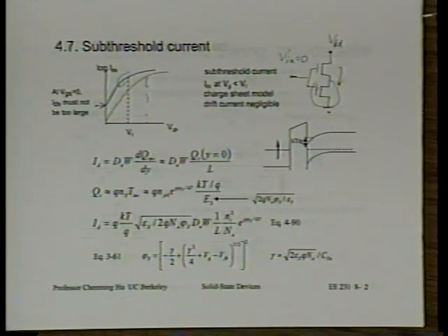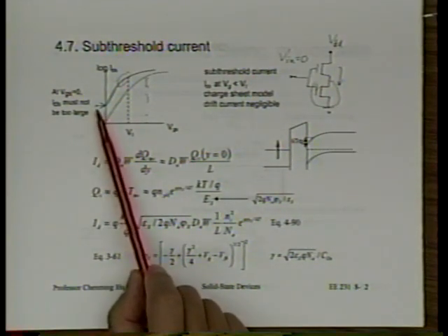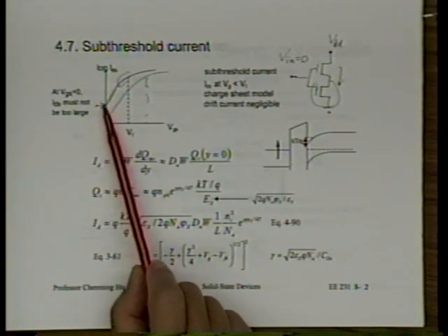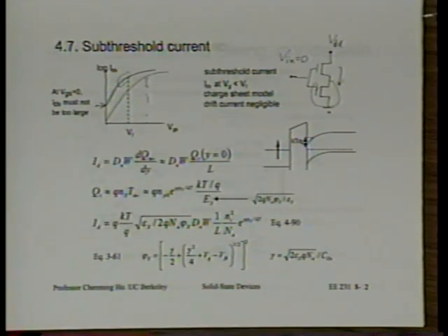Say again? But it requires a higher supply voltage. What do you mean by requires a higher supply voltage? Could you clarify? When you increase the VT threshold voltage, it usually requires a higher supply voltage. And that's definitely a no-no in the sense that reducing power supply voltage is required by the need to suppress or control the power dissipation. Power dissipation, in a way, is what motivates this discussion so far, or we use that as motivation to justify why we want to control this value, to reduce power.